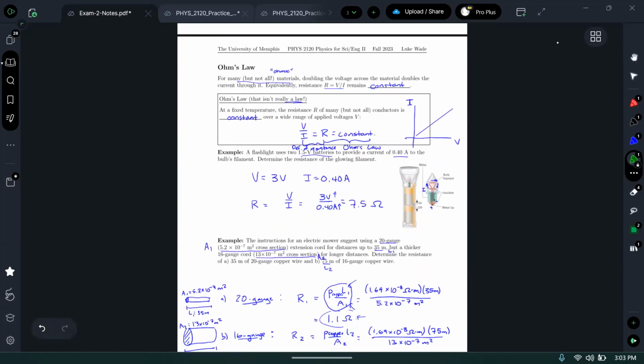Ohm's law, big thing about it is that it is just saying resistance is a constant. And it's not true for all materials, it's true for ones where it's true, just based on experiments. If you apply a certain voltage, you measure current, you keep doing that for different values of voltage, and you find that current increases proportionally so that the ratio of the two, this slope, is constant. That is a material or a specific conductor that obeys Ohm's law.